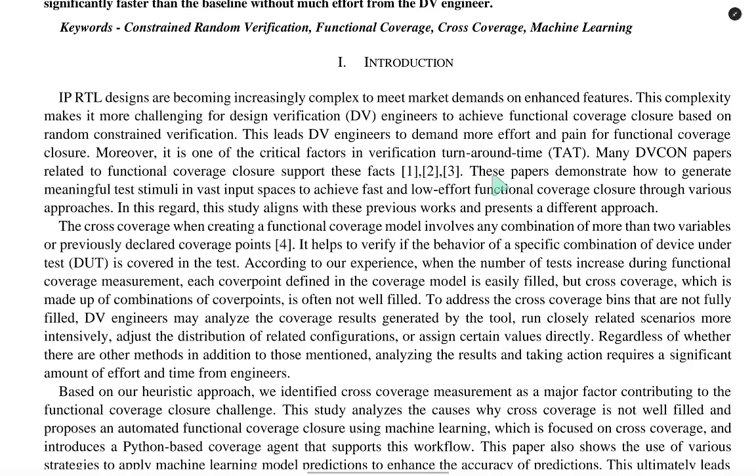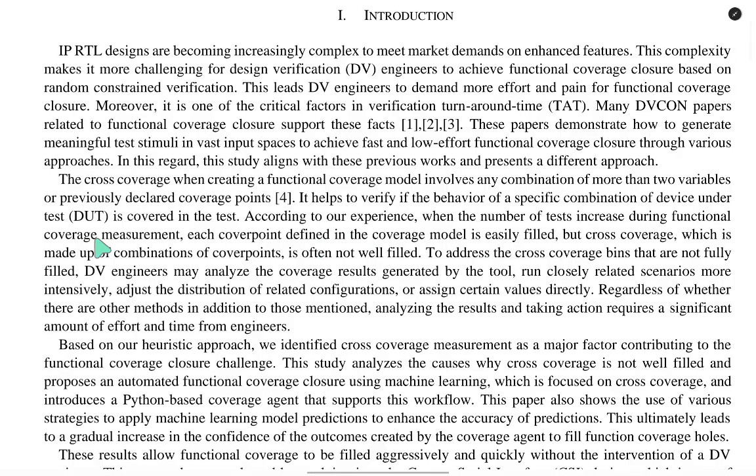These papers demonstrate how to generate meaningful test stimuli over vast input spaces to achieve faster and lower-effort functional coverage closure through various approaches. In this regard, this study aligns with these previous works and presents a different approach. The cross coverage, when creating a functional coverage model, involves any combination of two or more variables or previously declared coverage points. It helps to verify if the behavior of the specific combination of the device under test (DUT) is